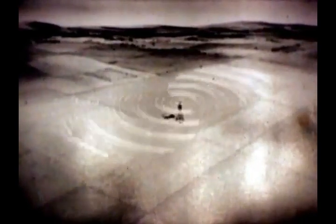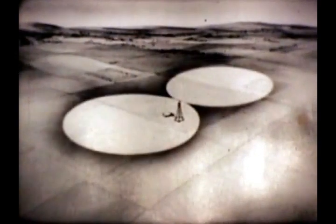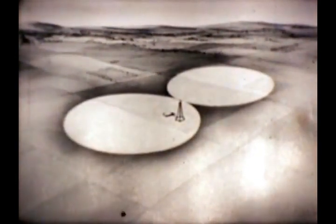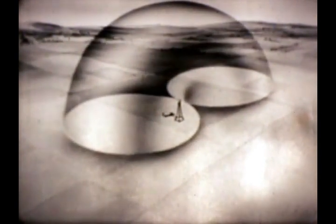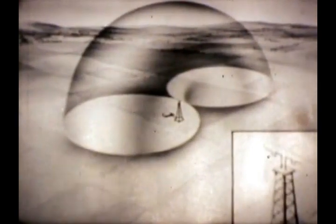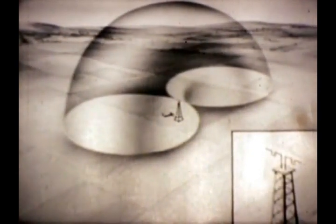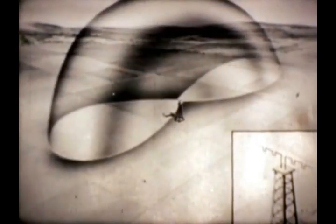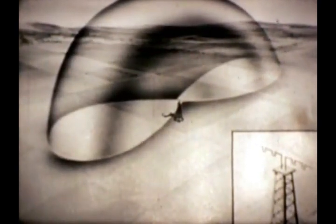Thus, the transmitted radio wave pattern resembles, horizontally, two paddles projected from both sides of the array. Vertically, however, the pattern has the shape of a donut. The broad pattern is produced by a small number of elements. The collinear array can be made even more directional by adding more elements. These added elements sharpen the wave pattern. The result can be compared to whittling down the width of a paddle.